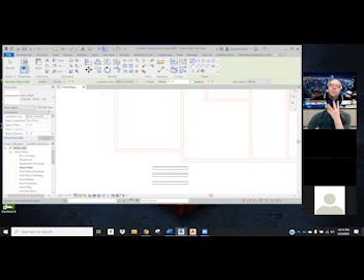So what I want you to do is change that to Finish Face. Let's do Finish Face Exterior. Okay, Finish Face Exterior. I think that's what I want. I'm second guessing myself a little bit because I got a little off my notes, but that's okay.